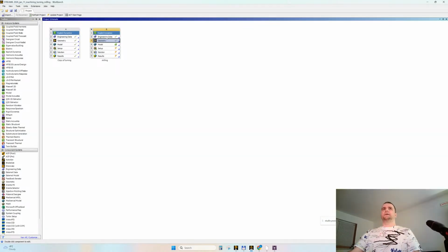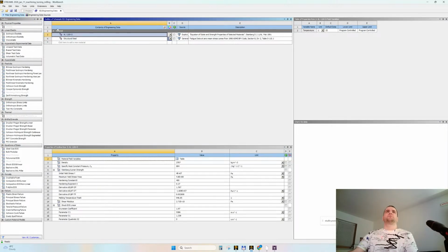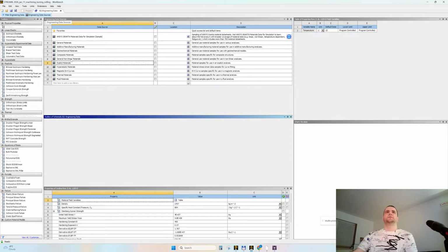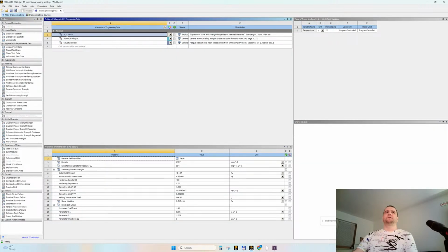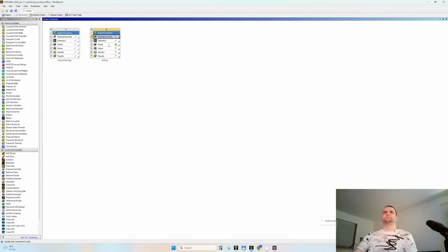And regarding the engineering data, let's choose also another material. Let's say general materials. Let's assign a nonlinear aluminum, yes, instead of what we had before. Let me delete here. Yes. And double click.